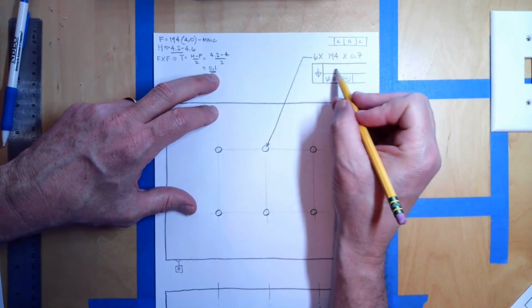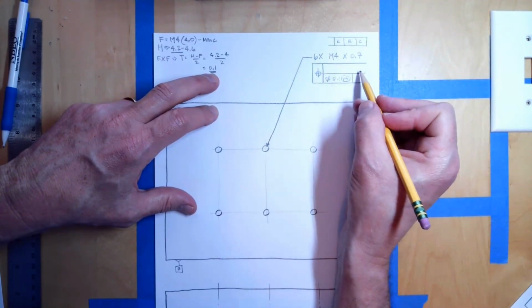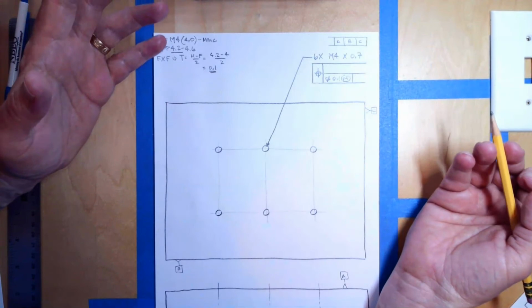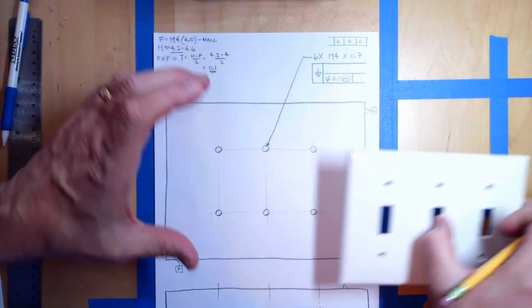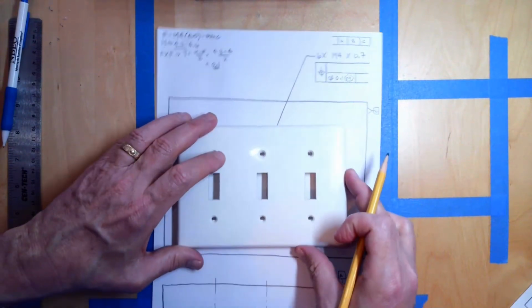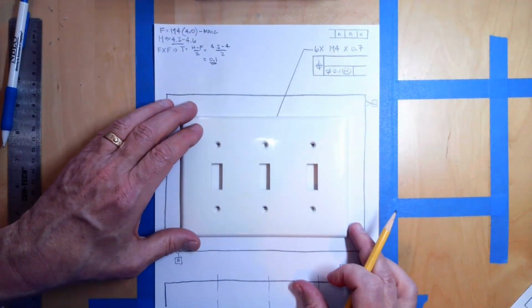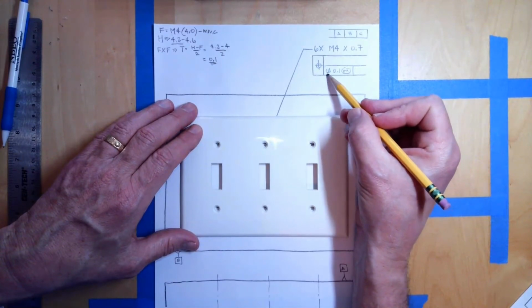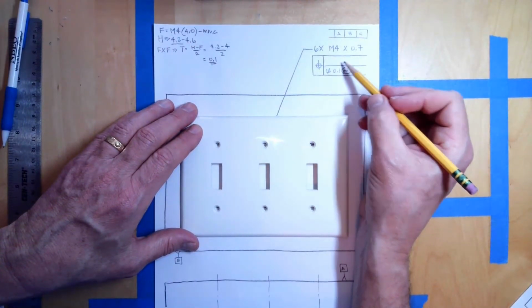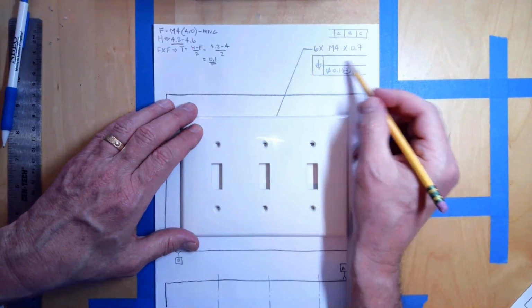So now I have my pattern locating tolerance zone. And here, there's not an equation for this. This is just where we get to say how tight or how restrictive we need this to be. Since the holes are going to be 0.1 tolerance zone, I need to be more than that.